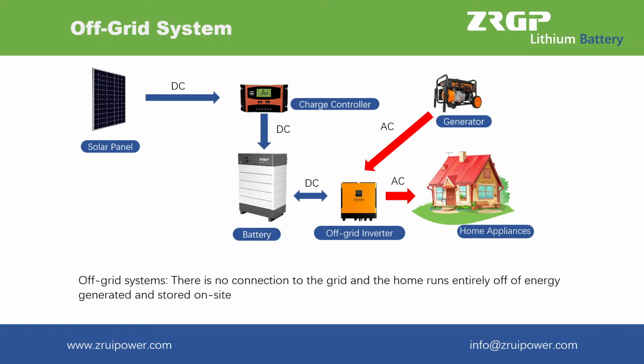On the contrary, if you cannot connect to the electricity grid, you should choose off-grid systems. An off-grid system is not connected to the electricity grid and therefore requires battery storage. Off-grid solar systems must be designed appropriately so that they will generate enough power throughout the year and have enough battery capacity to meet the home's requirements, even in the depths of the winter when there is generally much less sunlight.